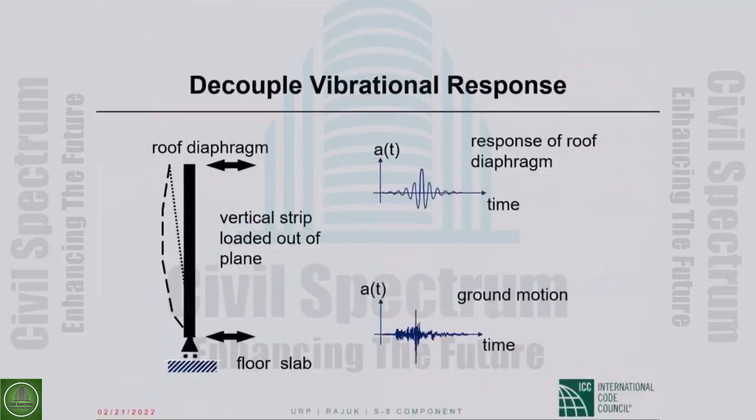They do not move together. So the out of plane wall is doing that, and the diaphragm, if the base acceleration follows this history, the diaphragm displacements will probably look like that.